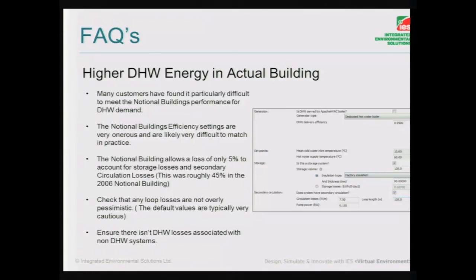To get the sort of efficiency levels that are being employed in the notional building, you'd probably be looking at an instantaneous point of use gas-fired DHW heater, which is just not going to be practical in so many applications. So that's an area where a lot of our customers, where they've got a DHW dominant building, are really struggling to match those same levels.